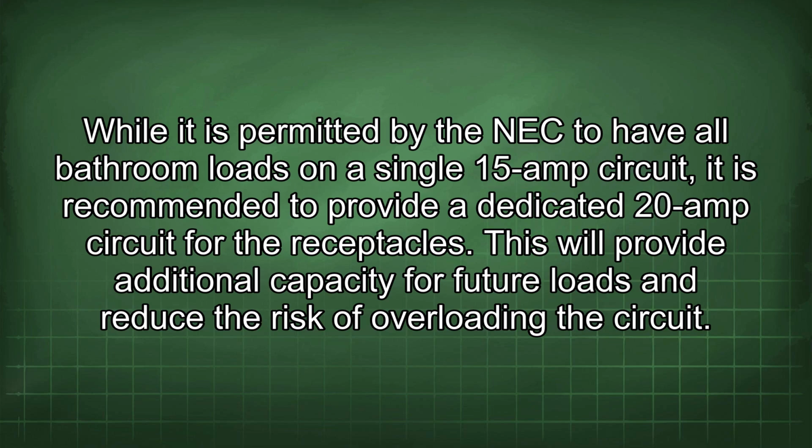While it is permitted by the NEC to have all bathroom loads on a single 15-amp circuit, it is recommended to provide a dedicated 20-amp circuit for the receptacles. This will provide additional capacity for future loads and reduce the risk of overloading the circuit.